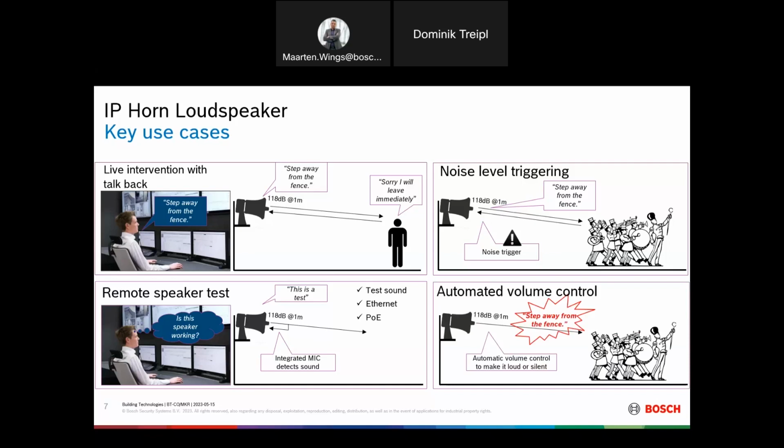So another thing is also the speaker has an automated volume control tuning. So what is that useful for? So if suddenly the ambient noise level increases, then also the sound that the speaker is producing to address the person near the speaker needs to be adjusted, because else the sound of the speaker will not be heard if it is on the same level as the noise itself. So a good example of this is a train platform, for instance.